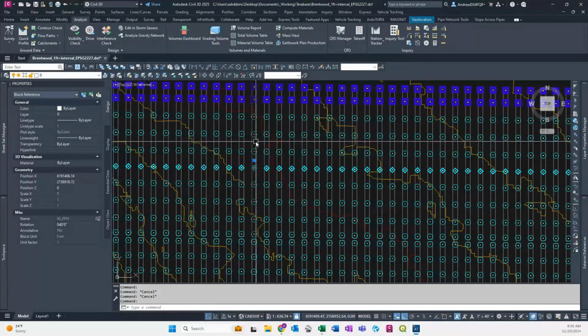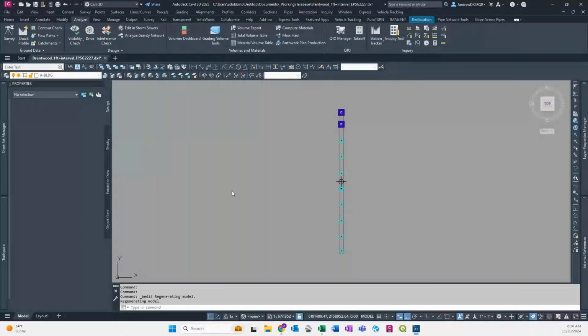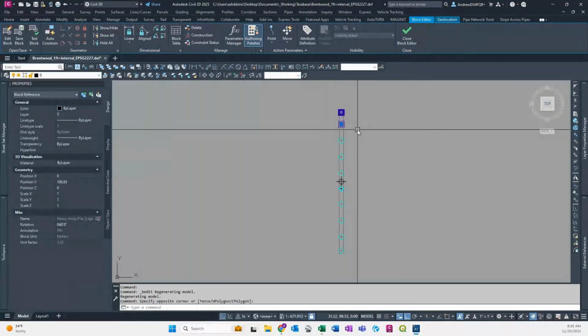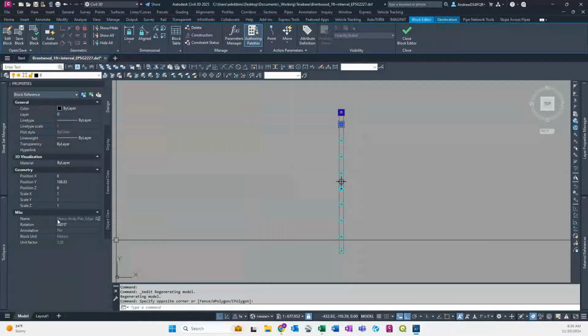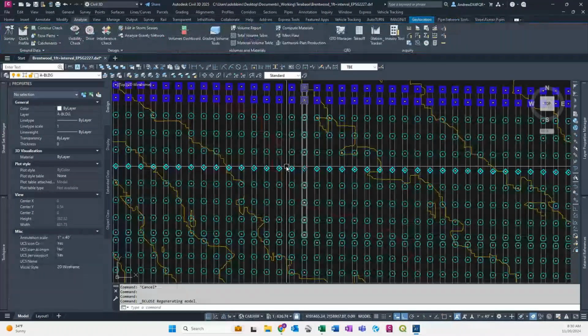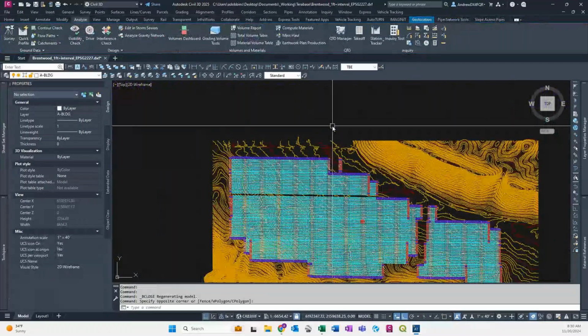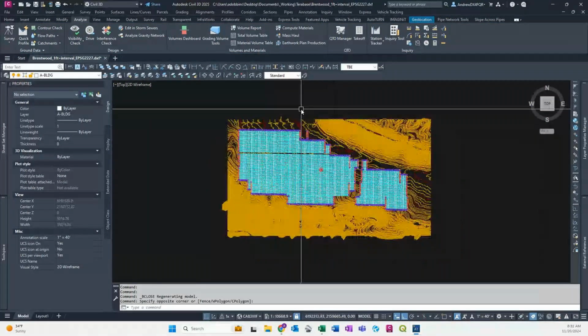And then if I open up that CAD block, each one of the piles is a nested block within that CAD block, again with unique naming to help identify the type of pile that's needed in each location. I'll back out of there, and I've got Terrain Pro ready and queued up to load this in.